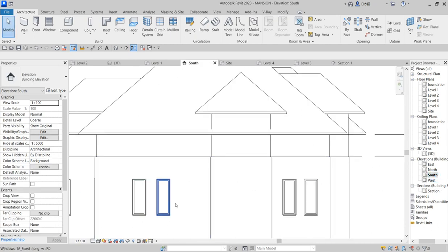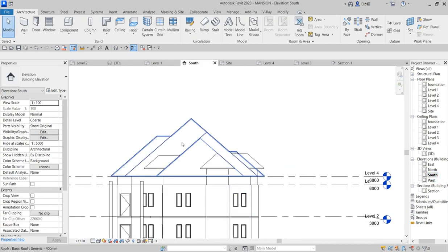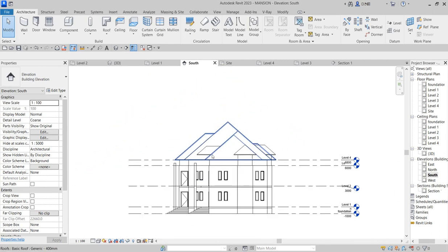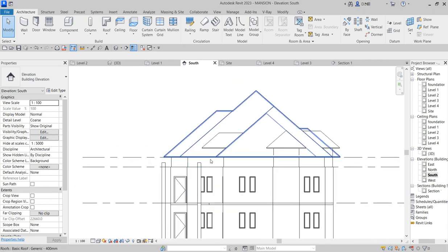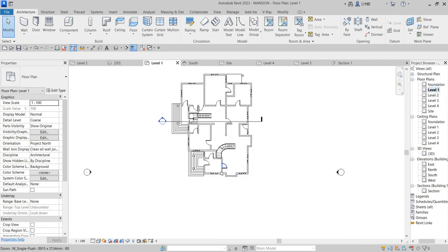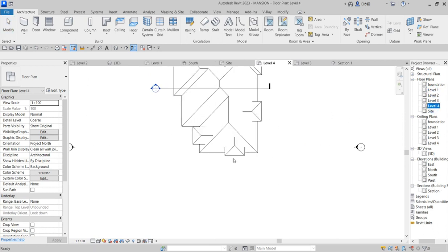So the next thing we want to do is now we want to put fascia all around this particular one before we now start doing the ridge cap and whatever that is needed. So what we do here is that you click on fascia. How do you do that? So you go back to what you used to do by clicking level 4.